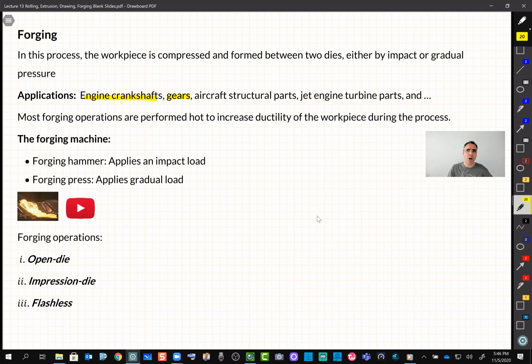Nobody makes gear out of tungsten, but just for the sake of discussion, tungsten, you saw powder metallurgy is very common because melting it is difficult. We prefer to work with powder to make tungsten tools. Let's say you want to make gear. So between forging and powder metallurgy, if the material is tungsten, then most likely you go with powder because you need a lot of force to forge the original material to make gears.